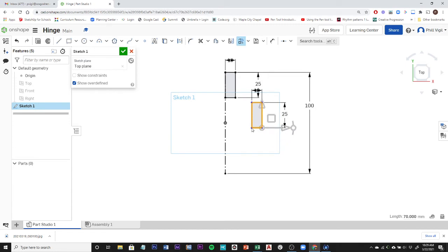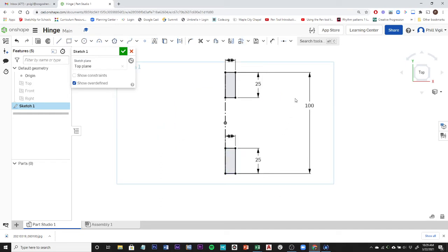I don't want that corner, I want this corner. So I'm going to go ahead and drag this point over here. Then I can drag using this square until it snaps into place. So I want that to snap right there. You'll see what the result will look like kind of in a ghosty manner. And then when you click anywhere else, it will actually perform the transform. So now it's placed it there. So now I have two ends of one hinge.